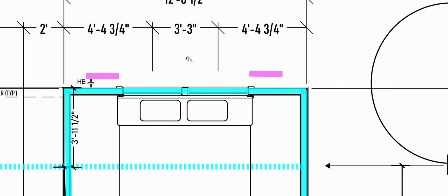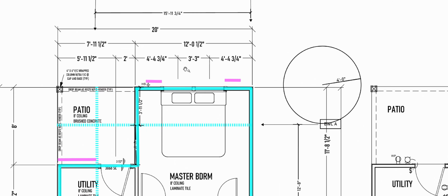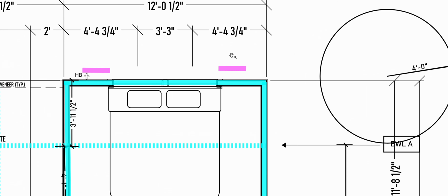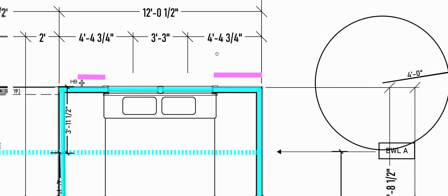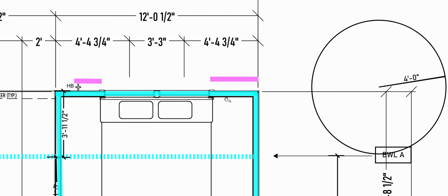So I'm going to check real quick and pause the video and come back with the number on if I can fit a panel next to the window or not. Okay, so I checked the numbers, and what the table says is if I have an 8-foot ceiling height and the window opening height is, in this case, a 5-foot window, so 60 inches, then that means I can put a 24-inch panel next to the window. So as long as I have more than 24 inches here, I'm just going to use one full panel next to the window. Yeah, I'm almost 3 feet.